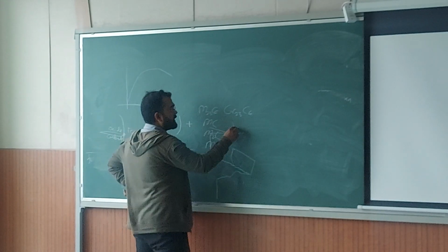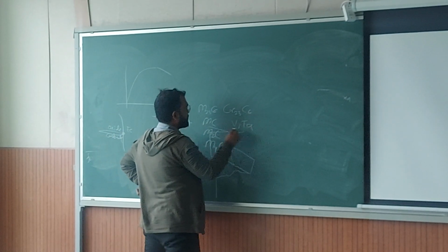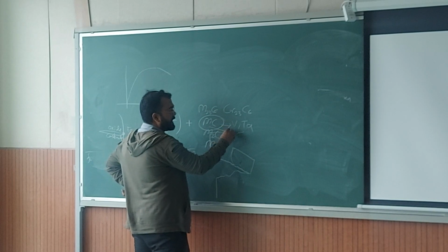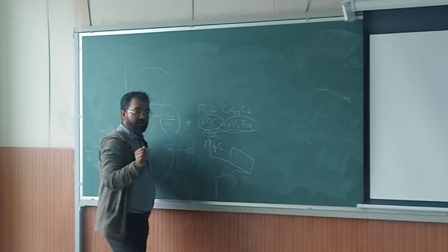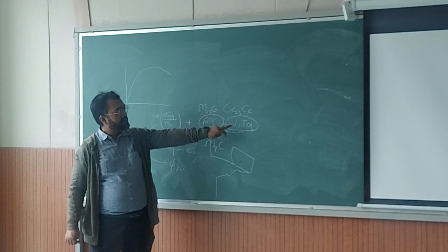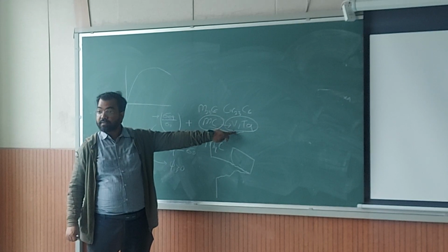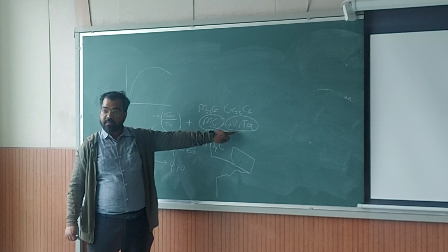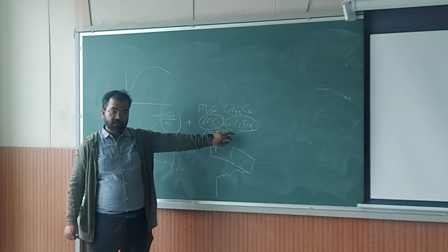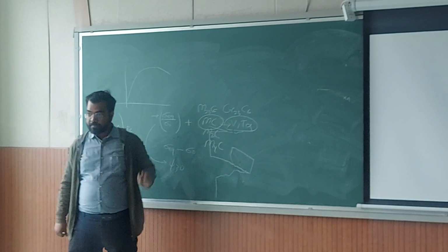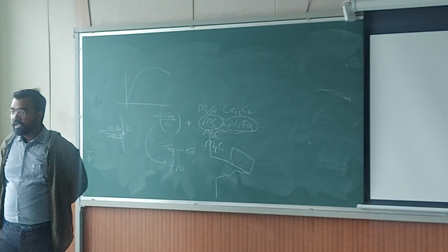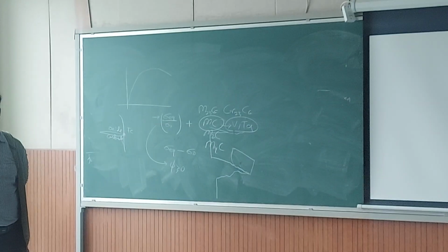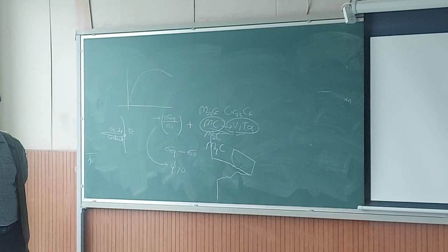And vanadium and tantalum, they form this type of carbide. And these carbides are even smaller than this one, and they will not form at the grain boundary, pre-austenitic grain boundary. They will form at the lath interface and in the size of nanometer because of the kind of heat treatment given